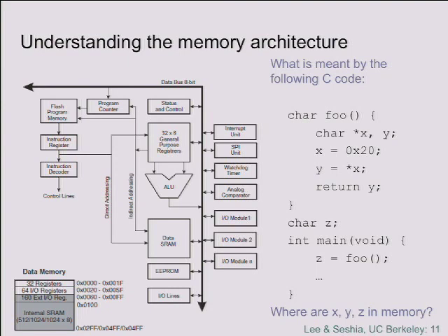The program memory is slower, but it also has a limited number of writes. Okay? So probably a decent compiler wouldn't, by default, without you going to some lengths, right? You probably would have to force it to use the program memory. How would you force it to use the program memory? Suppose I really want Z to be in the program memory.